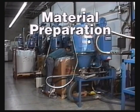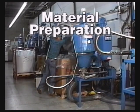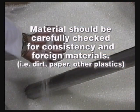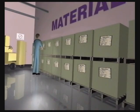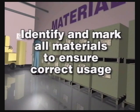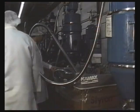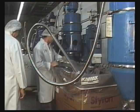Plastic resins require preparation prior to processing. Materials must be carefully checked for consistency and for foreign materials such as dirt, paper, and other plastics. In all cases, it is extremely important to properly identify and mark plastic containers to ensure correct usage. Visually check the plastic pellets before they are put in the machine and notify your supervisor if the material appears to be contaminated in any way.